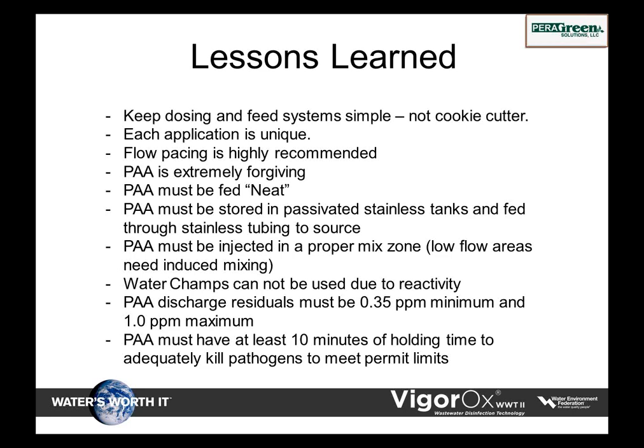Flow pacing has to be done. It's highly recommended. If not, you can use a controller or a monitor. But again, I would prefer doing flow pacing. It's extremely forgiving. You can see the levels, 52,000 to 290,000, never change dosage. The key here is you have to feed it neat. Forget using mixers, forget using dilution water. The key is when you have a 12 and 15% solution, you're feeding it 120,000 or 150,000 parts per million at that point source. Again, in 5 seconds time, we saw a 25% reduction in fecal levels. That's how fast the product works.